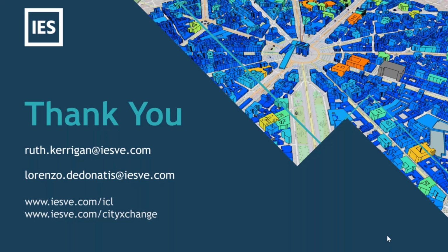That's exactly the reason why, with deep renovation, the idea is to have multiple benefits from additional renovation. Once you insulate the floor but not the wall, you will still have a huge thermal bridge there. If you do both, you also take care of insulating the corner between the ground floor and the external wall. In this way you are addressing not only the U value of the single element, but also the thermal bridge, reducing the overall heat losses in the building. The thermal bridge is calculated by the software, and reducing it influences the heat losses a lot.